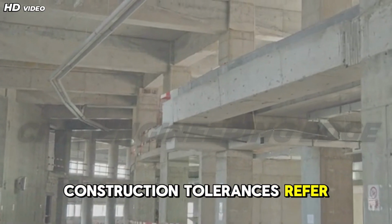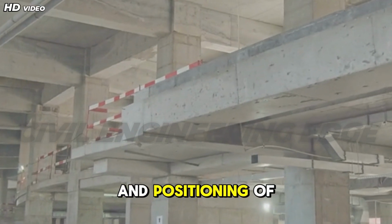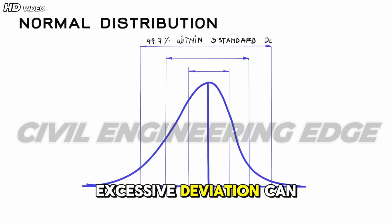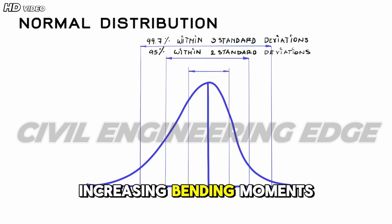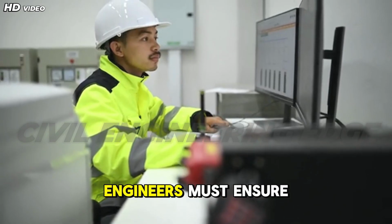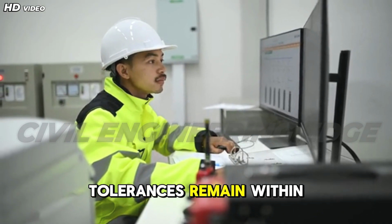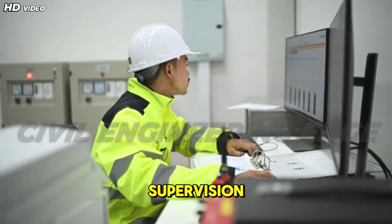Construction tolerances refer to acceptable deviations in dimensions, alignment, and positioning of columns. Excessive deviation can introduce unintended eccentricity, increasing bending moments and reducing load carrying capacity. Engineers must ensure that tolerances remain within permissible limits through proper setting out and supervision.